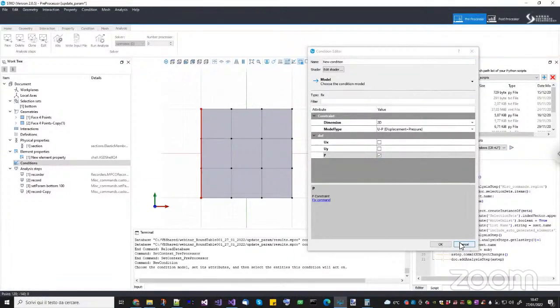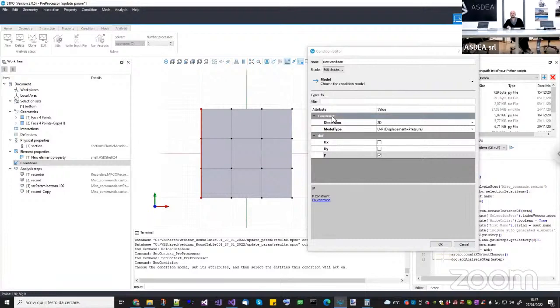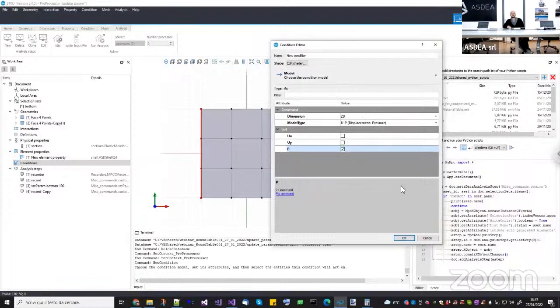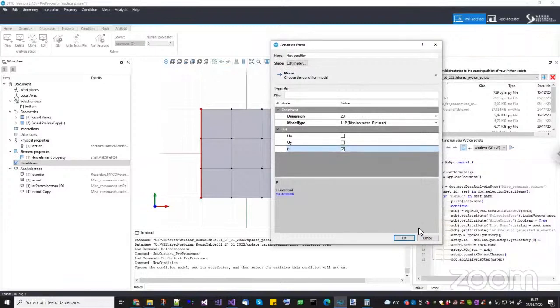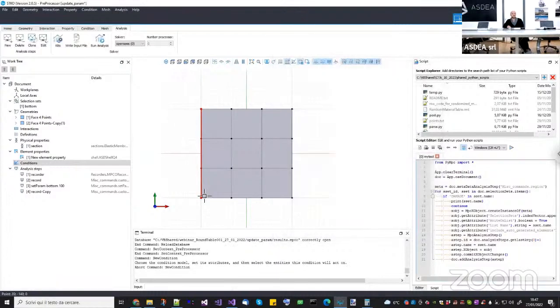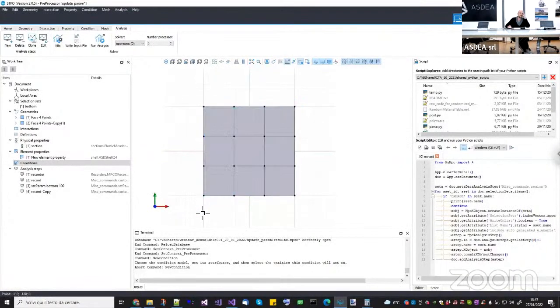Yeah, actually I'm modeling a soil, and I'm giving an earthquake excitation, so I need to have that liquefaction condition for piles, and I need to analyze it. So fixing it to 0 is not sufficient for you? You want to fix it to a finite value? Yeah, I need to fix it for a finite value. So for a finite value which is not 0, you can use the SP constraint. But I don't know if the SP constraint in STKO has support for the P value, because if it does not, you can do it by a Tcl script.